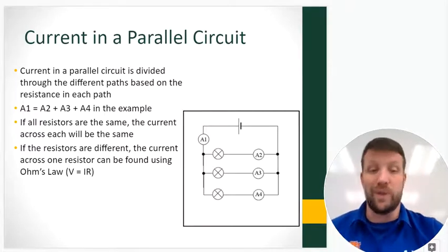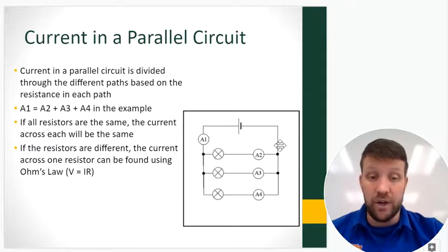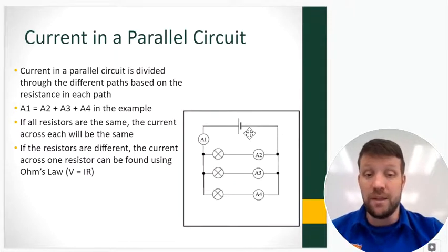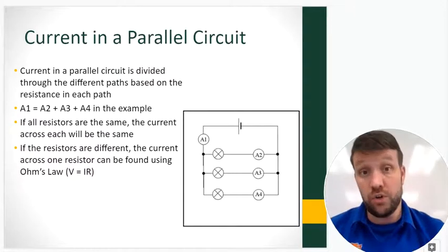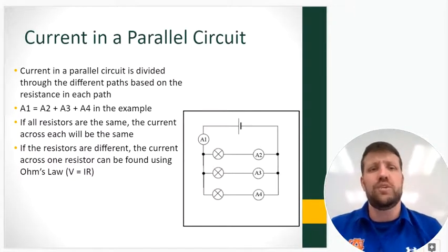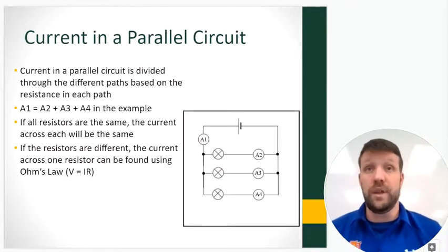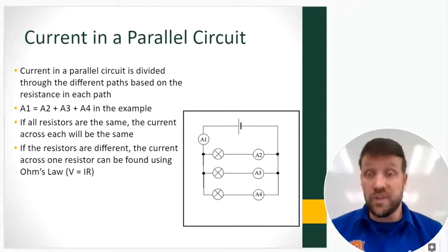it was water flowing. If I put a bunch of water flowing down this path, well, if some of it branches off here, and some of the water branches off there, and some of the water branches off here, but all those branches come back together, then before it gets back to the battery, I'm going to have my total current again, okay? So just think of current like it's water. However much is flowing through one branch plus the other is going to come back together